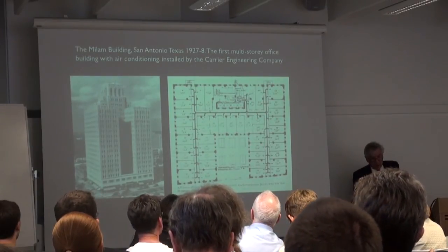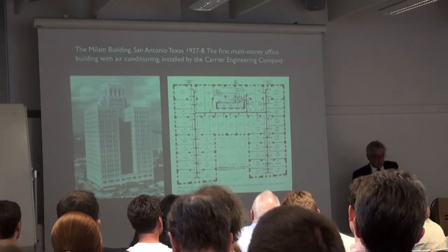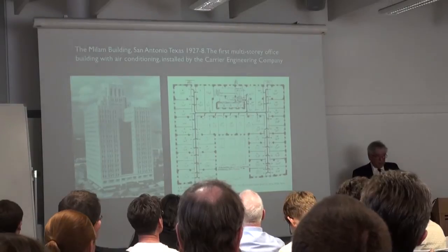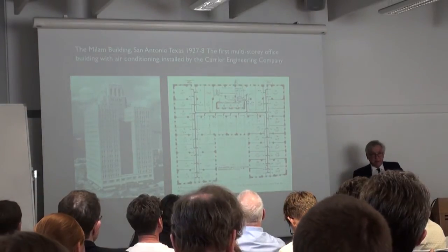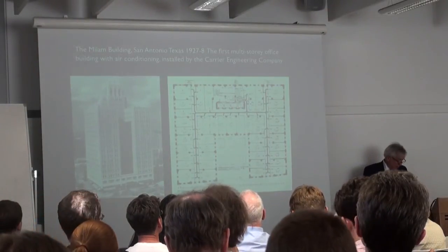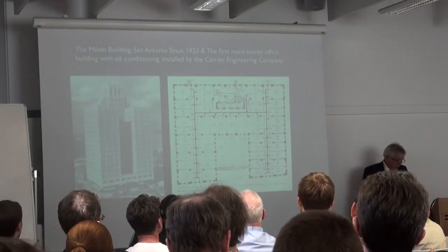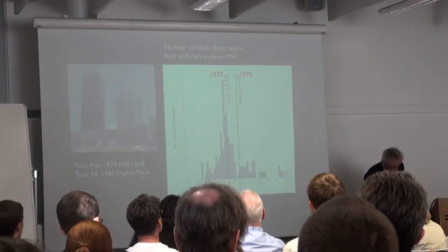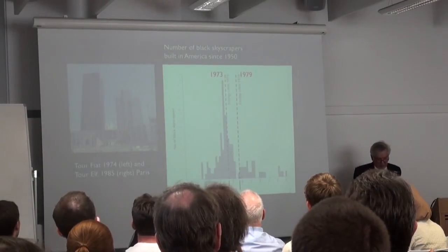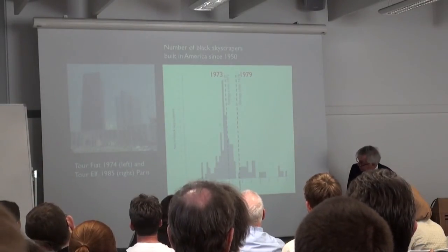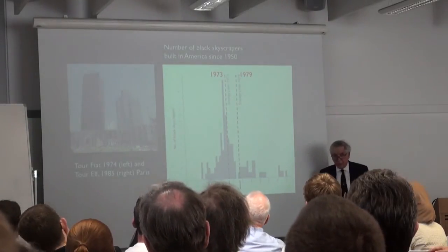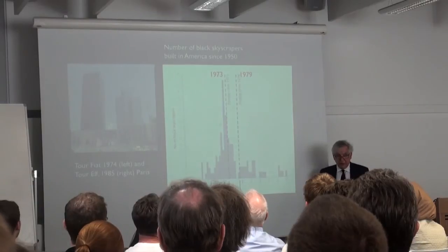As you all know, masonry-clad facades were replaced with glass. Glazing ratios went as high as 70%. Facade U values rose to values 3 times higher. Huge heat losses in winter. Overheating from solar gains in summer. There was a fashion, I was going to say short-lived, but it wasn't so short-lived, an insane fashion for black glass skyscrapers.